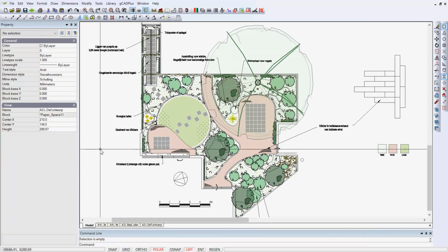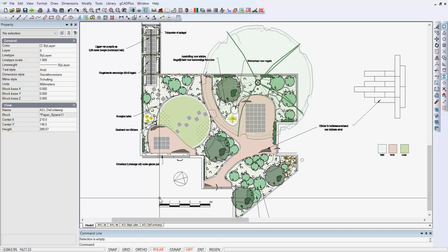Now, a useful thing to do, so what I'm saying here, transparency in the drawing won't print to a PDF writer at high resolution at a fixed scale of 1:100. We can get by including a scale bar, as you see here, and using that save as PDF, but the print is not exactly 1:100 because when we do the save as PDF, we can't nominate the sheet.